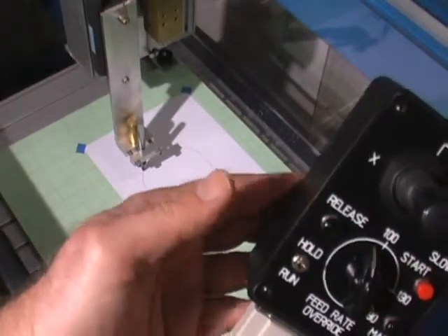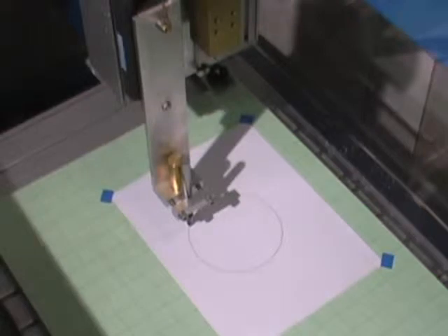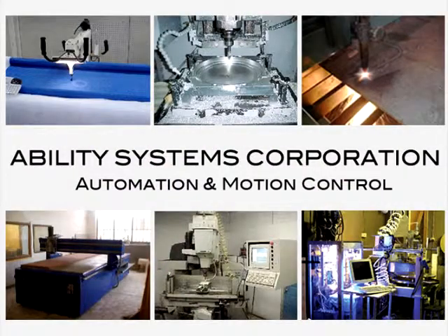When motion is stopped, however, activating the release switch provides the application program with the opportunity to exercise additional control, such as G-code controller's option to recover from broken tools, change offsets, and to resume from a prior location along the tool path. A separate session will be devoted to recovery from interrupted operations. But now that we've covered the implications of instantaneous and accelerated motion, and controlled and uncontrolled stopping, it's time to explore multiple motor control in our next session, entitled Interpolation.